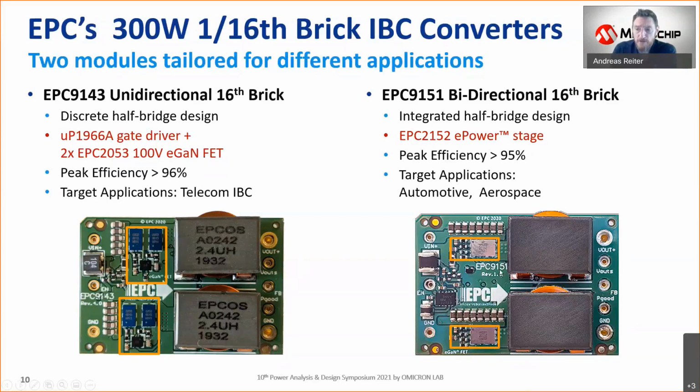So the first advantage is that we can operate the switches at their natural maximum speed. All the parasitics which come into play here on the left in the discrete design, so parasitic inductance of packages, of resistors, gate drive resistors, all of this usually requires us to slow down the gate so that we are never really achieving the maximum switching speed that could be achieved by operating that switch.